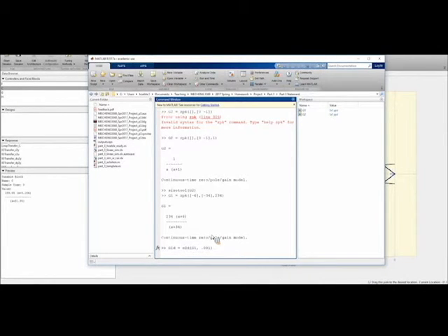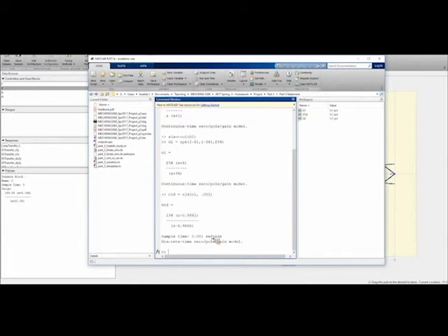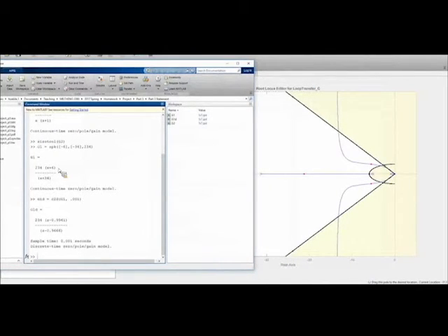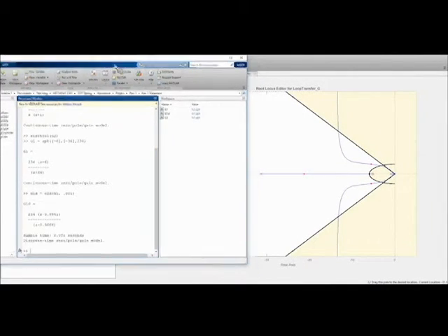You type this in, and it kicks out an equation for you, and you see that what was in a variable of S is now in a variable of Z. When we work in discrete time, Z is how a computer works. That's just the frequency variable when you work in discrete time. There's a lot more to that, and I'm glossing over it very quickly, but that is what the form would look like. Doing inverse Laplace transforms is fairly difficult, but doing the inverse transform in discrete time is actually really simple.